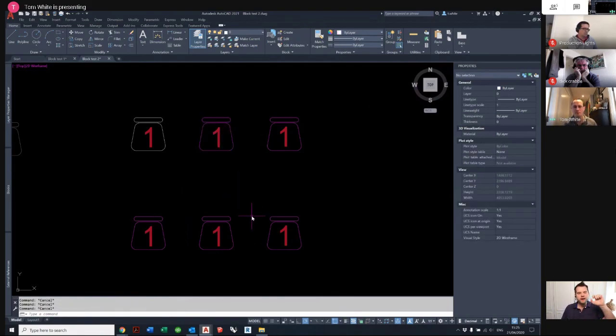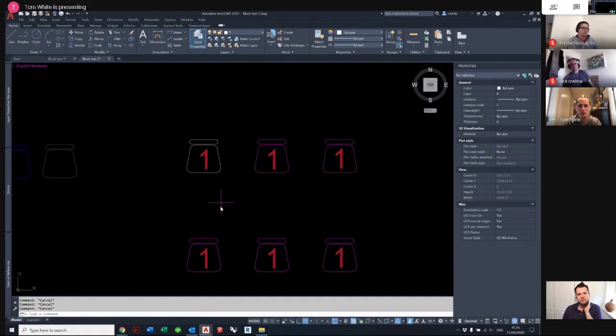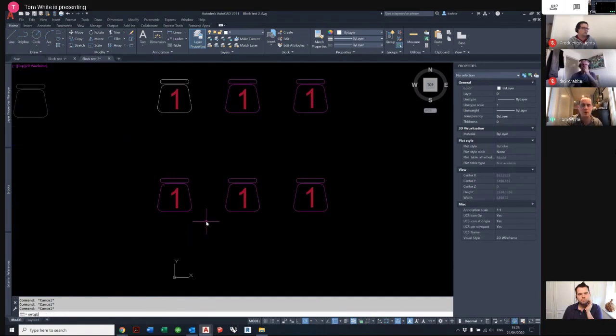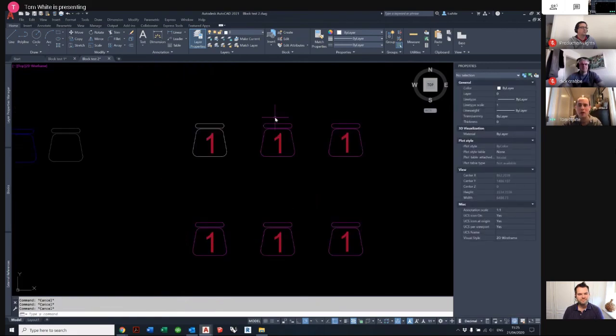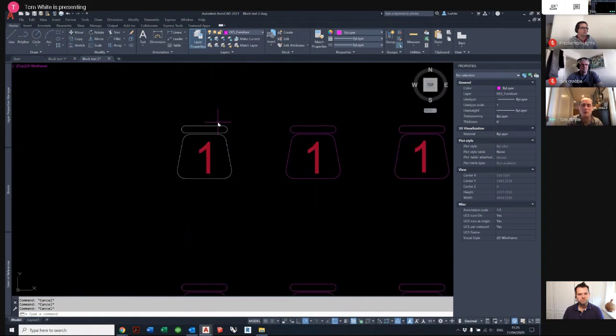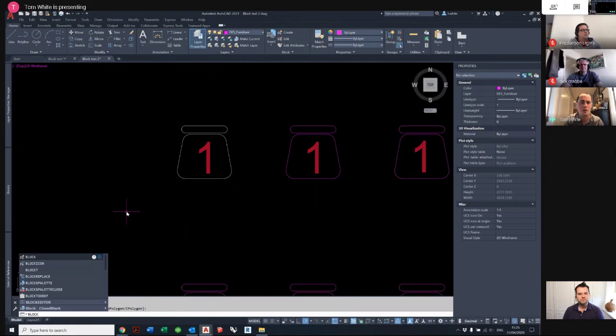Just to recap on that, how do you get it from the left-hand one to the center one? How do you create that block? Okay, so I would do set by layer. Yeah. So therefore, I've got this one here. You can choose the layer you desire it to go onto, and you use the block command. Whenever you're trying to do something in AutoCAD, and I've got an incredibly bad short-term memory, I just type anything in. If I've forgotten to do something, so in this circumstance, my end result is a block. So why don't I try and type block into the command line and press enter?